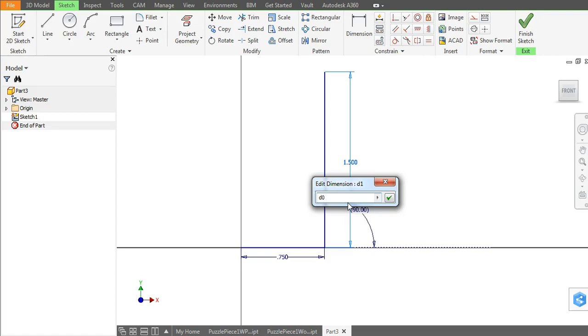So I can use my base dimension, that 0.75, which is the width of one cube, and everywhere I dimension now a segment, I can think about if I want it to be 1 cube, 2 cubes, or 3 cubes. If I want it to be 2 cubes in length, then I would say D0 times 2. It'll reference the base dimension, which currently is 0.75, but later might get changed to 0.5. And it will always take whatever this dimension, whatever that is, and double it, so that this always stays proportional in basically a 1:2 ratio.